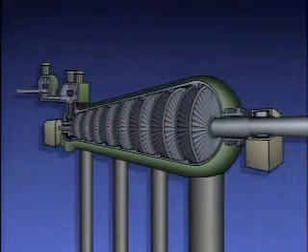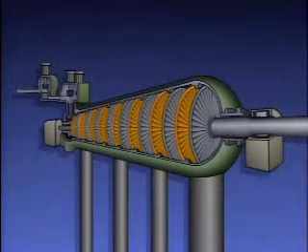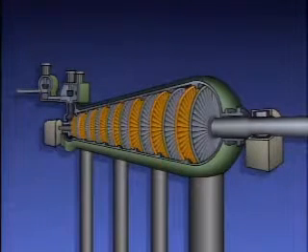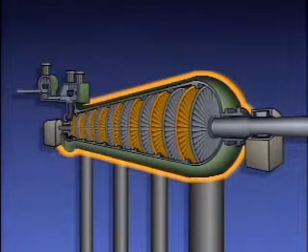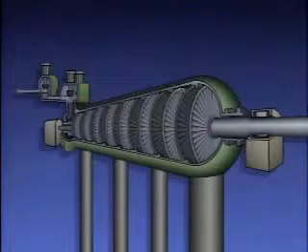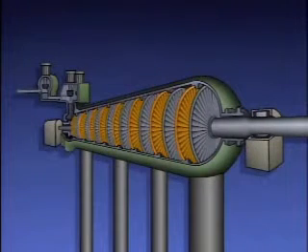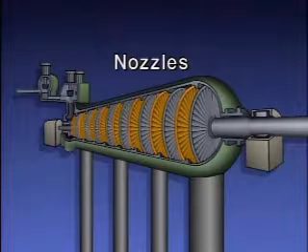Mounted to the turbine casing are diaphragms. They are positioned in the casing between the wheels. The casing and diaphragms are stationary parts of the turbine. Diaphragms are similar to wheels in that they are round hubs and they have blades. The diaphragm blades are sometimes referred to as nozzles.